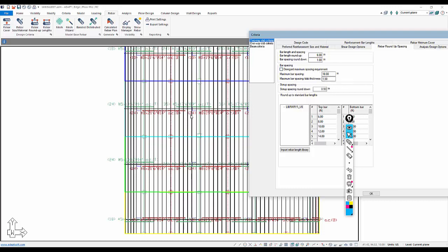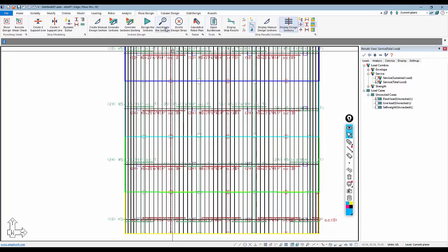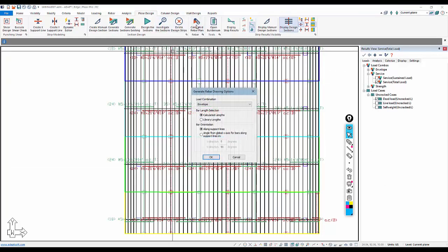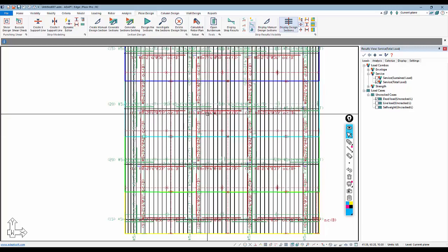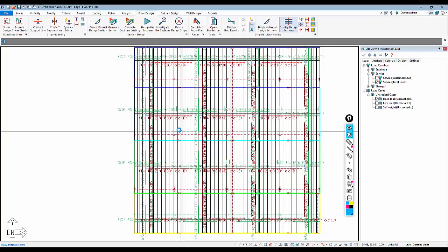And that's what's happening. It's actually adding 16 more bars so that they are spaced no more than whatever the minimum is of this setting. If I disregard this and I go back and calculate the rebar again for the envelope, you can see now we need 8 number 8s, and that's because I turned the spacing check off.